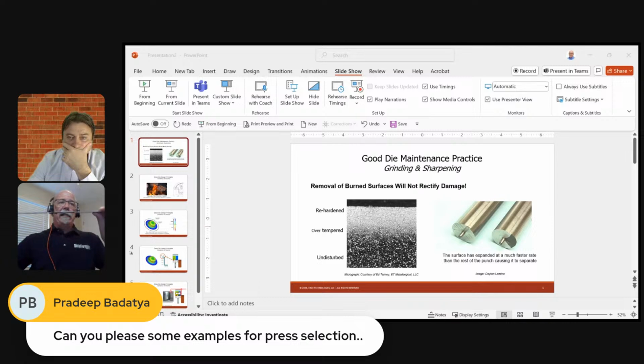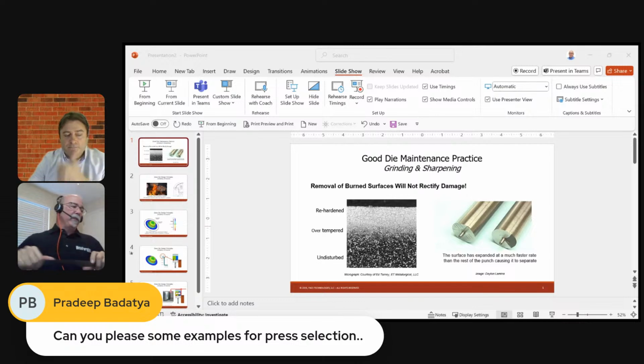If the material is feeding and I begin to feed and it buckles, I'll detect that buckle, and that sensor will shut the press down, because if the material buckled, it didn't progress on this end, I know I'm going to have a short feed. So that's another option. You can check halfway through the feed progression, or you can check on the entry side of the die, because if material is buckling, cutting that opening in the top of that feed shelf forces the buckle to come up in that area.